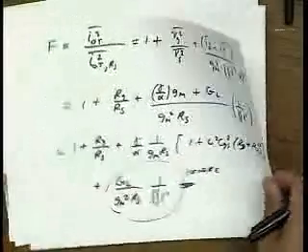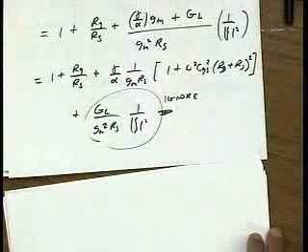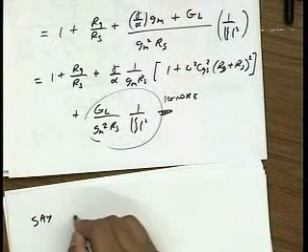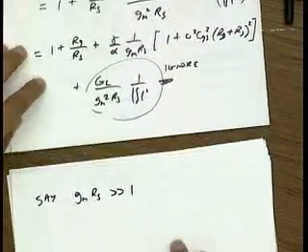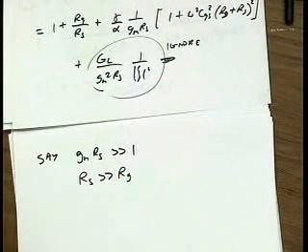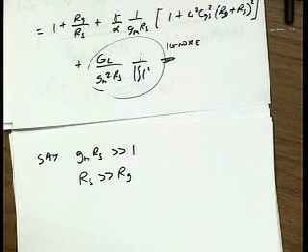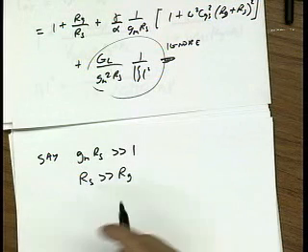Okay, so let's now simplify this expression a bit. I'm going to assume GM RS is relatively large. And I'm also going to assume that RS is relatively larger than RG. In other words, I've laid out my transistor in such a way so that RG is not big. Because remember, if RG is 50 ohms, your noise figure is already 3 dB. So really, you want to make RG much smaller than RS in a good layout.